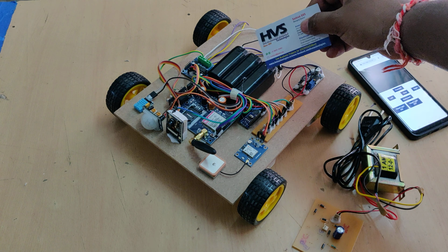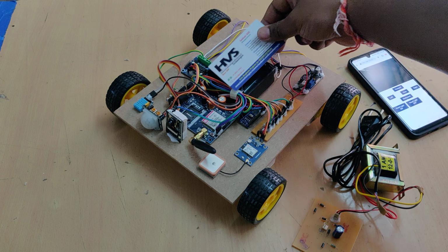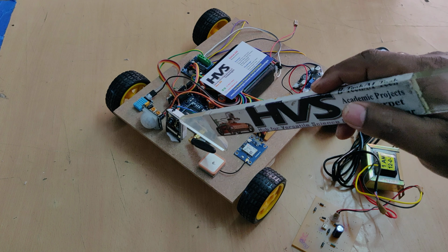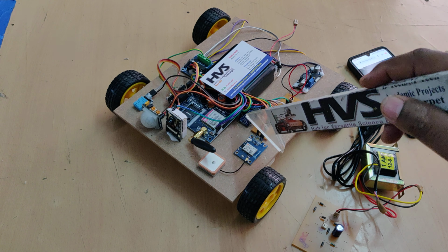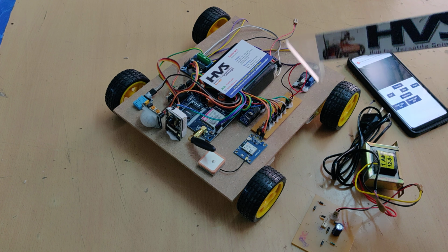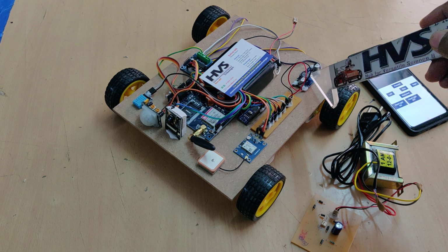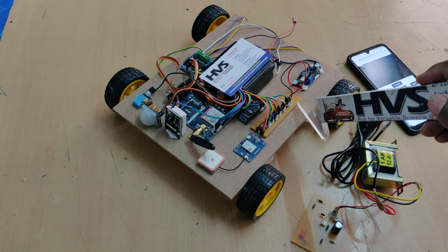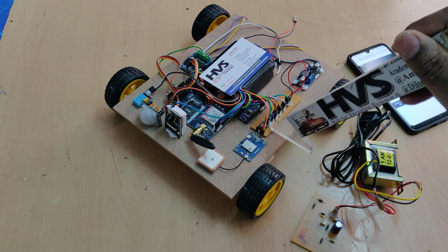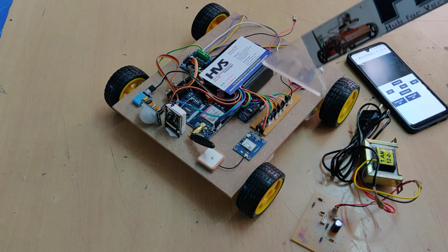As we can see, three 4-volt 1 amp batteries are in series, so we get 12 volt 1 amp. That is the operating voltage for the DC motors. But the operating voltage for our ESP32 camera, GSM, GPS and nano is 5 volts. In order to regulate that 12 volts DC to 5 volts DC, we placed the LM2596 voltage regulator. From there we are getting the 5 volts DC output. We are distributing the 5 volts power supply throughout this breadboard, and from here we distribute it throughout the input and output modules.